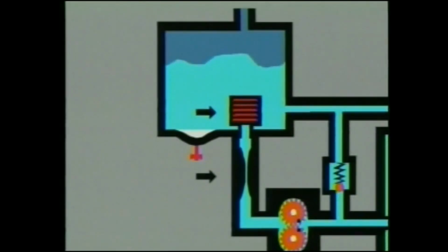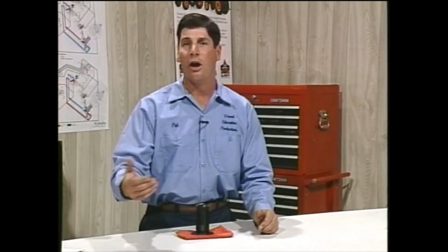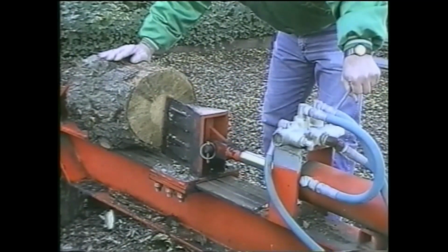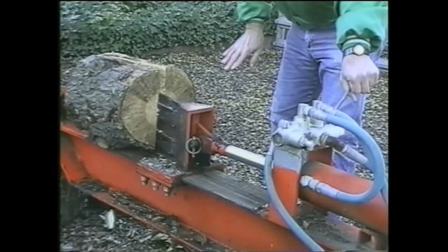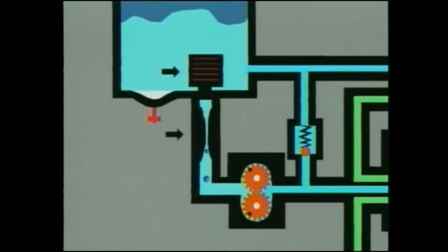This causes a defective suction hose to collapse and cut off the flow of oil into the pump. A slow cylinder response and loud pinging or cavitation noise then occurs. Cavitation is the high-speed compression or implosion of negative pressure vapor bubbles as these bubbles go from the vacuum or inlet side of the pump to the pressure side of the pump.